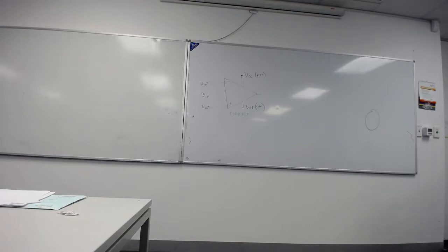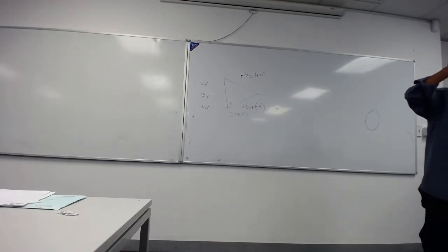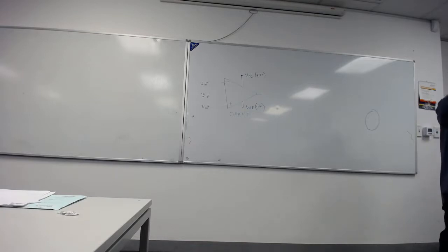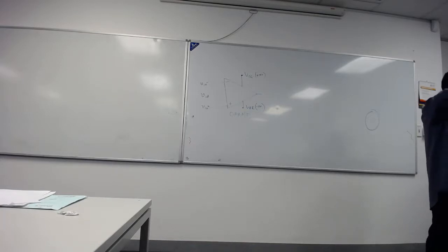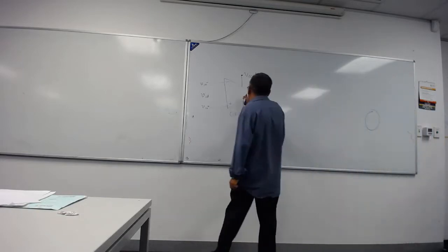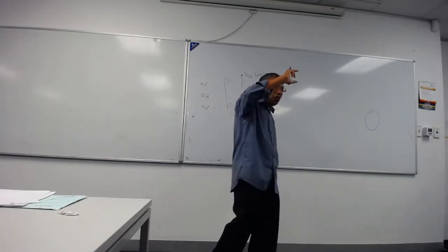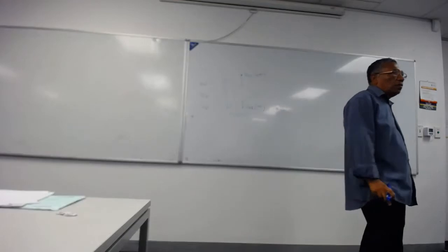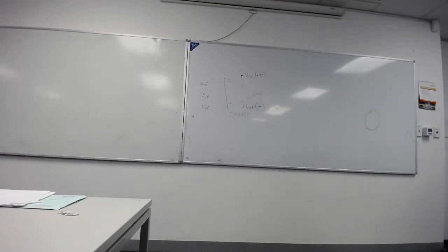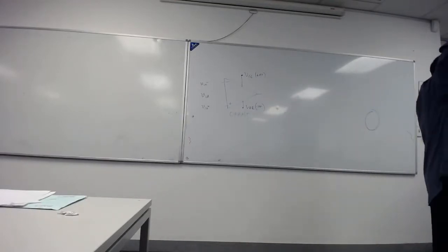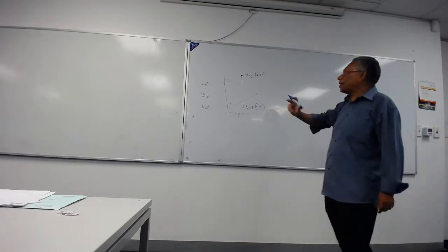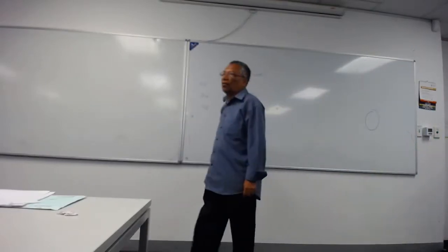So what it also means is that your transistor circuits are not perfect. All the transistors that you use to build op amps have certain voltage drops in there. Between the collector and emitter, there will be a transistor here and a transistor here, and there will be drops across them. Those drops will eat up part of your headroom voltage, and instead of getting 15, you'll get 13.5.